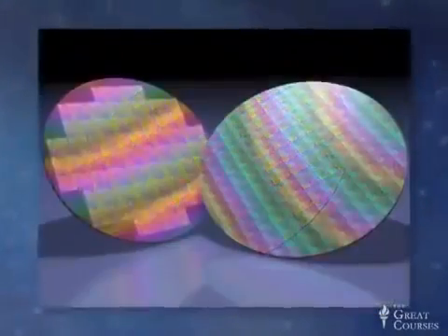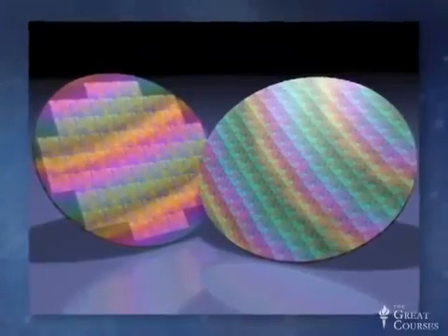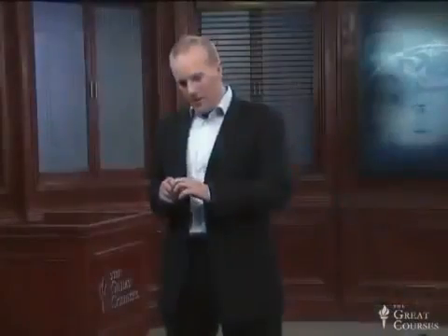And what that means is that if you can get light into it, which is the hard part with something with high refractive index, but if you can get light into it, then the light doesn't want to escape. It's tightly confined. It gets trapped inside. And it's that trapping and the multiple bounces that makes diamond have its characteristic flash of appearance. So in the case of silicon, what this means is that we can make waveguides that can meander across an integrated circuit, can take multiple bends, can go around loops, can go around tight turns, and they can do that very efficiently. And so silicon is proving itself out to be an extremely good mode of conveying light on integrated circuits. So that's looking very promising.